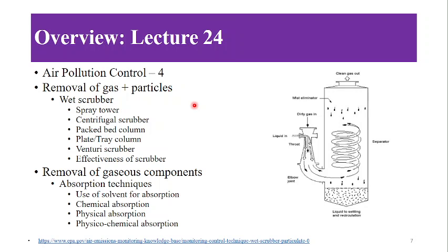There is contacting between the liquid and the gas, and because of that the particulate matter gets dissolved in the liquid and is thus separated from the gas.